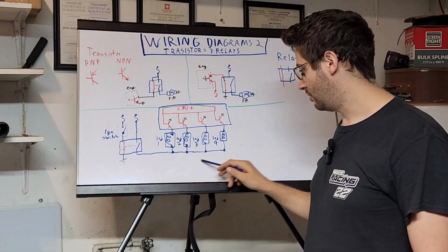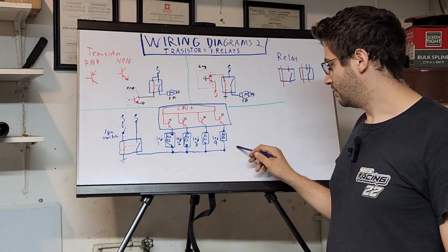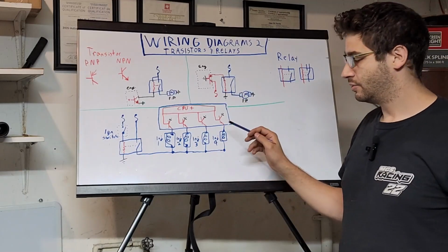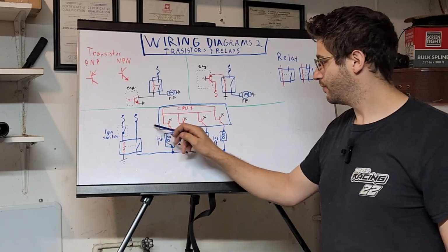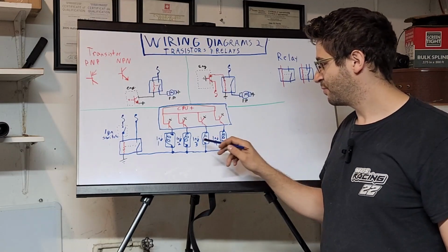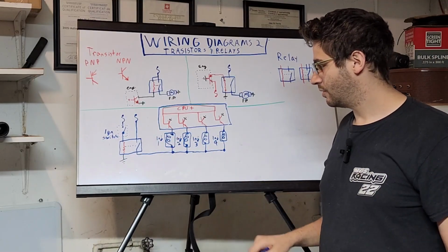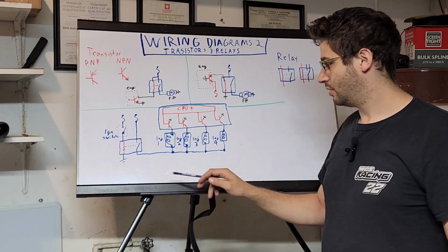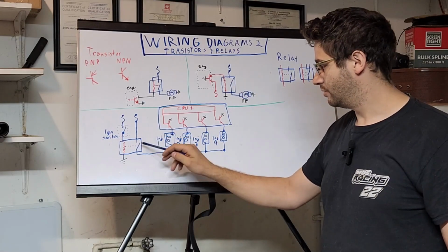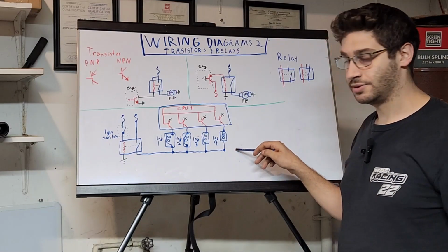So here I've taken a cutout of an injector circuit for a 4-cylinder. Here's a circuit on how injectors work with transistors. Ignition switch is going to close, and the relay is going to get energized and close, and it's going to apply power to the 4 injectors.